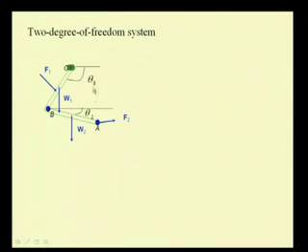The configuration of this link system can be defined by these two coordinates, say theta 1 and theta 2. And so, we call this as a 2 degree of freedom system, because you need two independent coordinates like theta 2 cannot be expressed in terms of theta 1, and so we need to define specific values for theta 1 and theta 2 in order to obtain the particular position A. So, any virtual displacement say consistent with the constraint B prime and say A prime has to be defined by defining both this d theta 1 as well as the angle d theta 2.